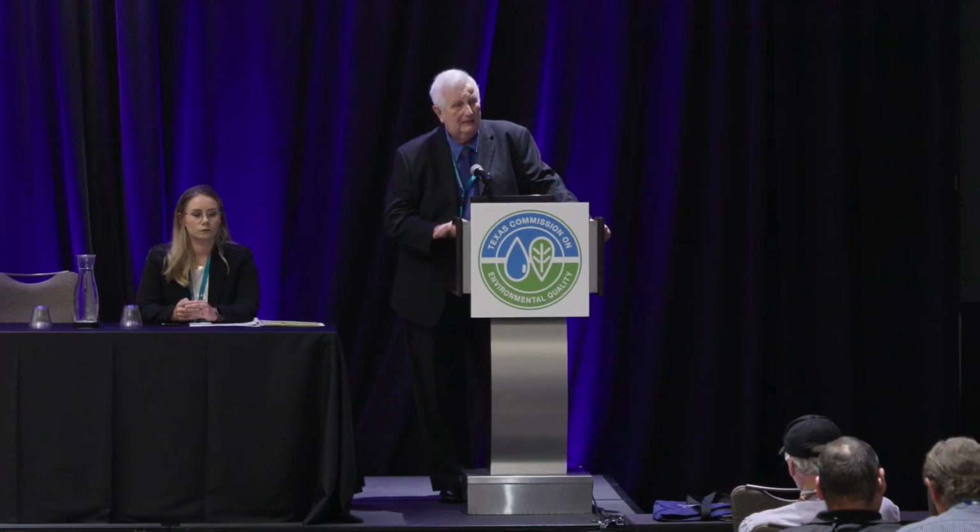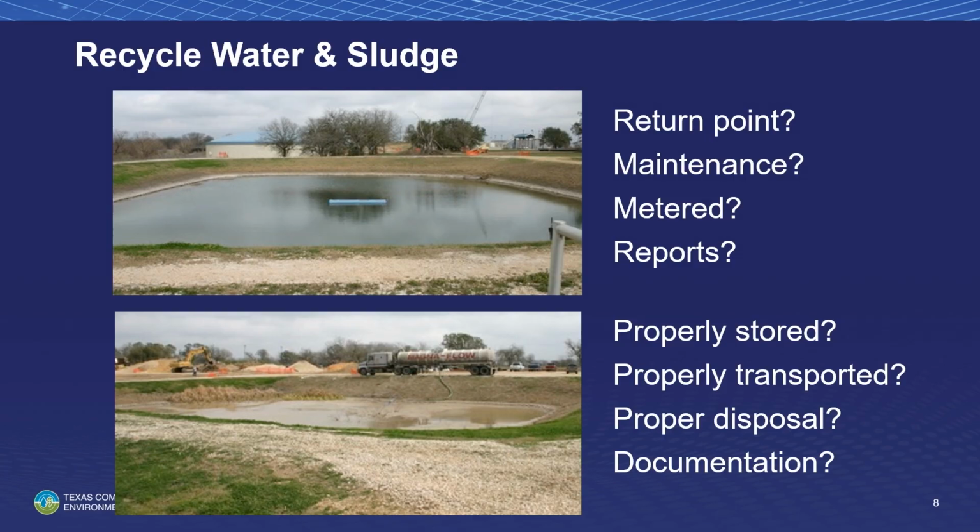If they get too full, those sludges can go septic pretty quick. And when they do, and you start doing return water from those things, well, they can get into an anoxic situation, which means that if you're treating for something like manganese, iron, and that kind of thing, and it gets discharged to these ponds, it can be reduced back to the soluble state. And then you kick on your feed water from these ponds to feed it back into your plant. Well, you're sucking contaminants back into your plant that you just treated for to begin with. So you can kind of screw up the conditions of your water source by not taking care of the maintenance on these ponds.